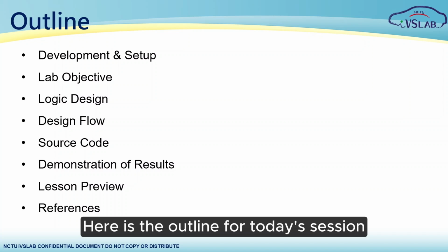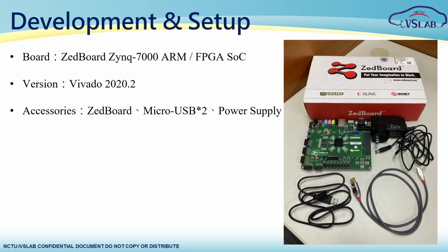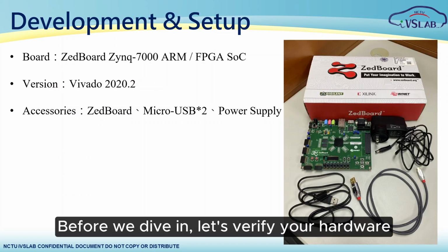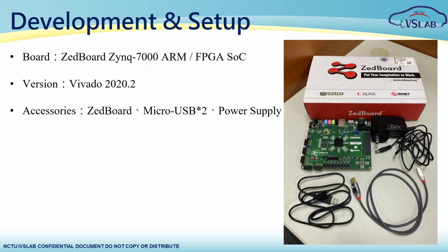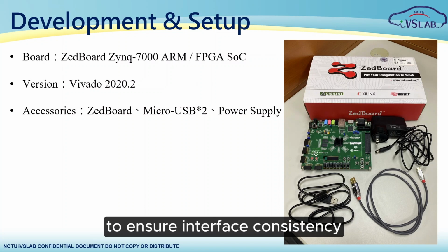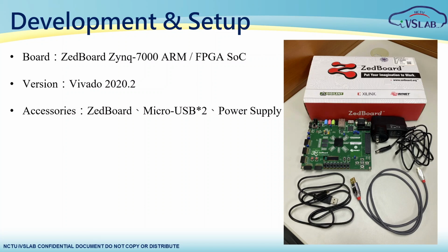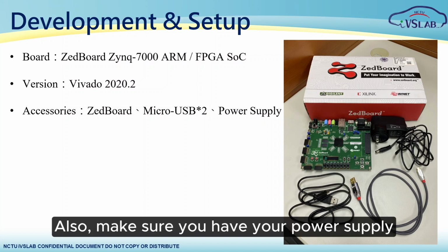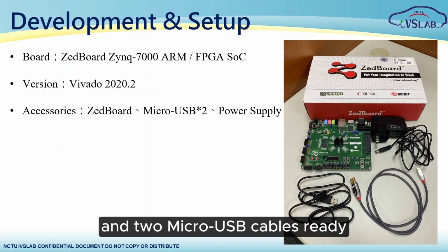Here is the outline for today's session. Before we dive in, let's verify your hardware. We'll be using the Xilinx ZedBoard. I recommend using Vivado 2020.2 to ensure interface consistency. Also, make sure you have your power supply and 2 micro USB cables ready.